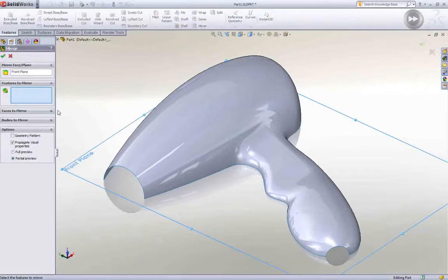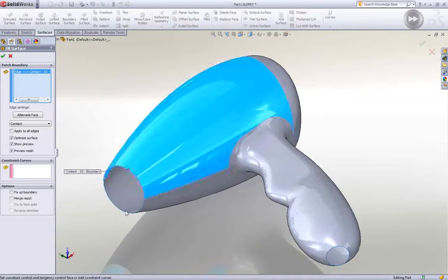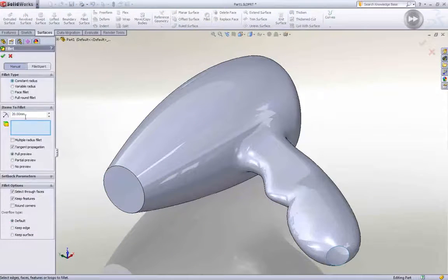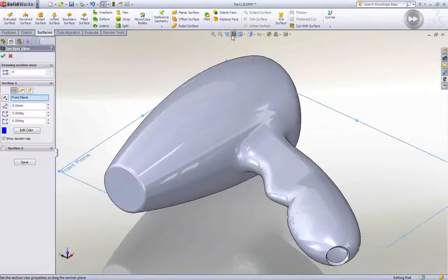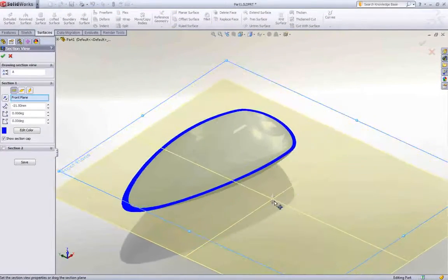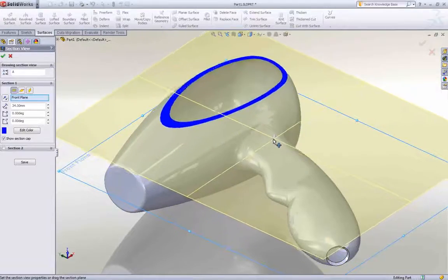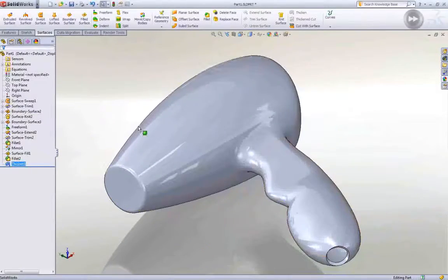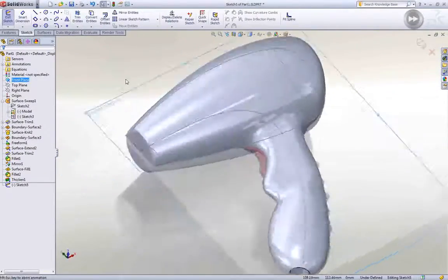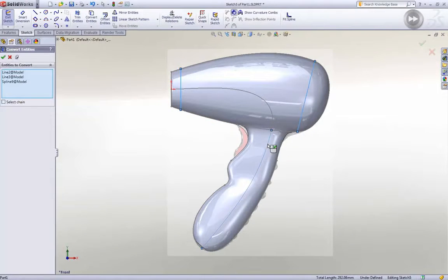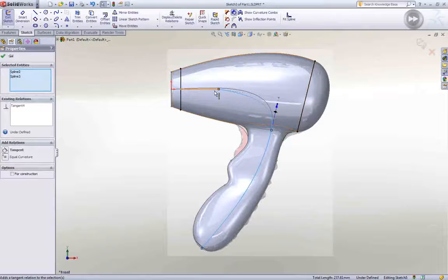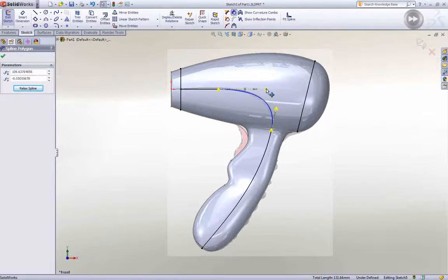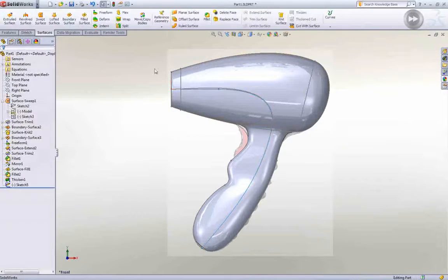The aesthetic design of the product is now complete, so we can start to add manufacturing details. Since the design is all driven from the same model and in the same environment, design changes are fast, predictable, and easy to do. This solid model of the design can now be split into individual components and either saved as an assembly or kept as a multi-body part, allowing you to continue adding features such as lips, grooves, and bosses, whilst ensuring all the parts fit together perfectly.